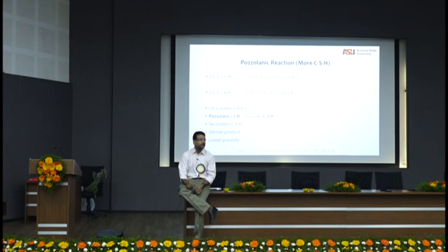Then why are we very worried about the amount of fly ash that you can go in? Assume that fly ash will take time to react, 90 days. Do a TGA, thermogravimetric analysis, of your cement paste after 90 days. You will still get calcium hydroxide there. You can't eat up the entire calcium hydroxide with fly ash. Calcium hydroxide also keeps producing.